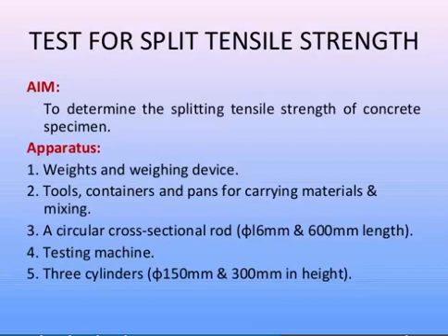Concrete specimen molds shall be made of steel and 3 mm thick. The mold shall be capable of being opened longitudinally to facilitate the removal of the specimen, and is provided with a means of keeping it closed while in use. The mean internal diameter of the mold is 15 centimeter and the height is 30 centimeter. The molds are provided with a metal base plate, and need to be coated with a thin film of mold oil before use in order to prevent adhesion of concrete.